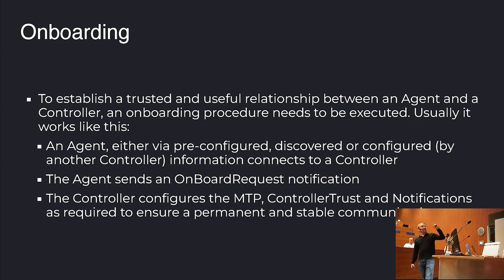And that is also quite important if you have multiple controllers, and you have, let's say, one controller that has a full view of all the devices in the field, and then you have certain use cases that you want to have implemented on a separate controller. Then this first controller could create a new controller object on a device, and then it can call the send onboard request message on the device, and then the device will connect to the other controller and send the onboard request notification and allow the other controller to configure this particular use case on the device and establish a trusted relationship.